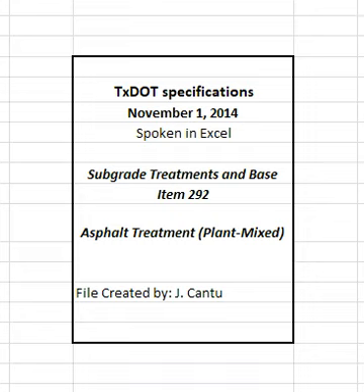2.2 Recycled materials. Use of RAP and RAS is permitted unless otherwise shown on the plans. Do not exceed the maximum allowable percentages of RAP and RAS shown in Table 2. Determine asphalt content and gradation of the RAP and RAS stockpiles for mixture design purposes in accordance with TEX 236F. The engineer may verify the asphalt content of the stockpiles at any time during production. Perform other tests on RAP and RAS when shown on the plans.